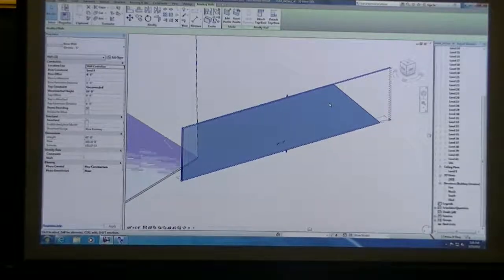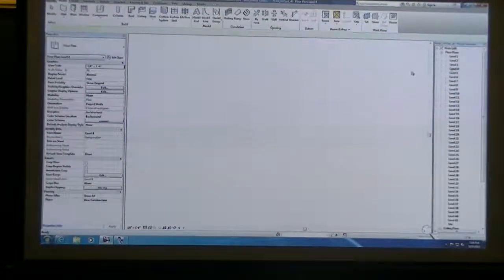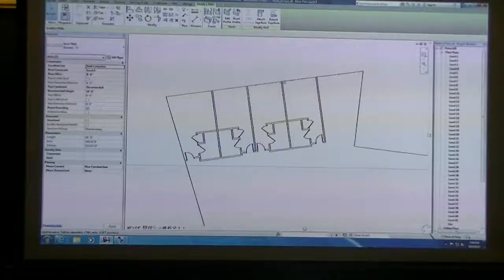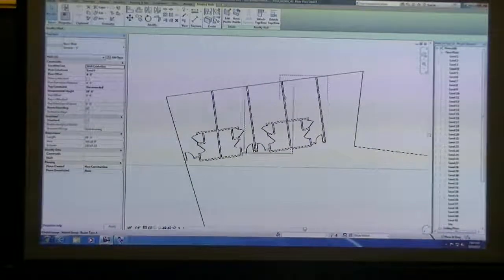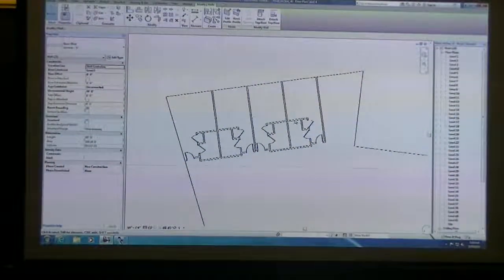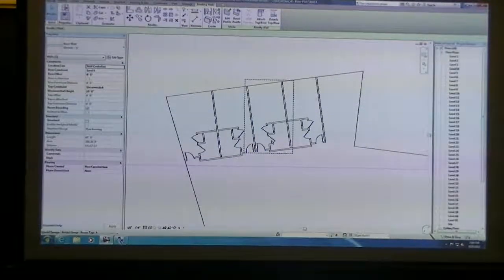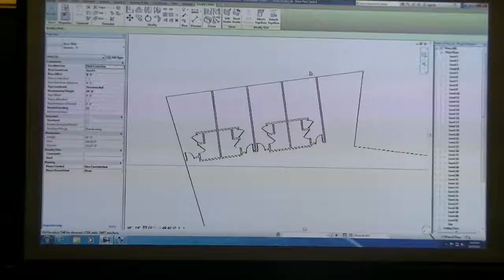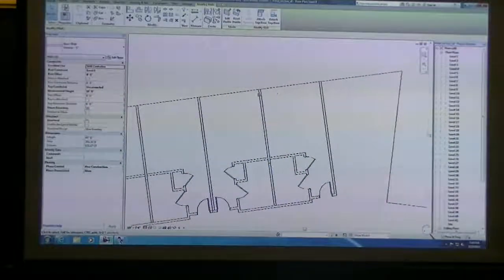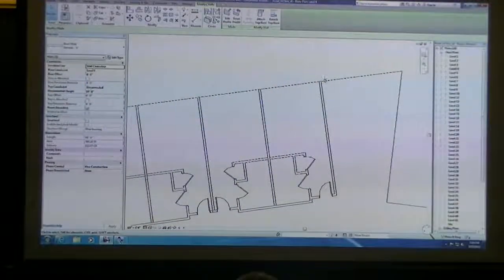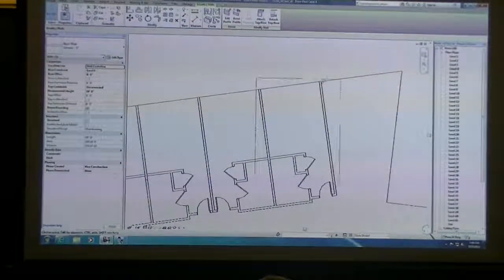Of course, if you have repetitive groups, you might actually bring your walls back. So if I was in level 4, if I knew that this wall was changing, and later on it's going to be out here to 3 feet out, my rooms might actually start to move out with the angle of the wall. I might not have perfectly stacked bathrooms, but you don't always have to have perfectly stacked things. You might have the same group move out with it, but you might also always stop this. You could stack these rooms all the way up, and then later on just come in and model an additional extension that might be part of the exterior wall assembly.